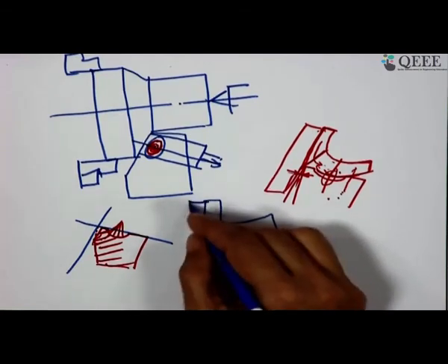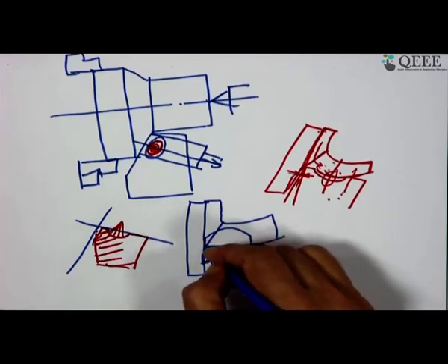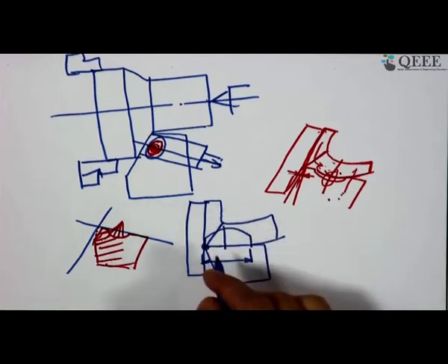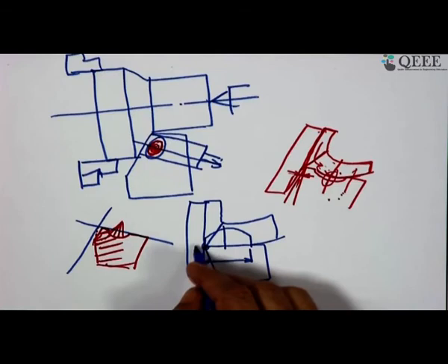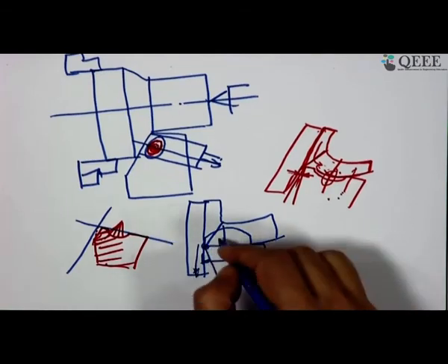Though this is the cutting edge, the temperature is not highest here; the temperature is highest at a point behind, for the simple reason that the heat at the edge is conducted away by the workpiece.